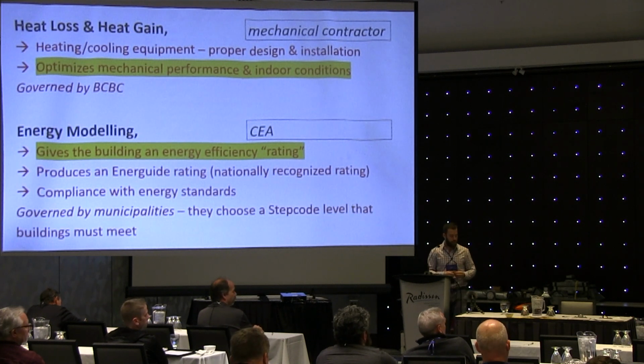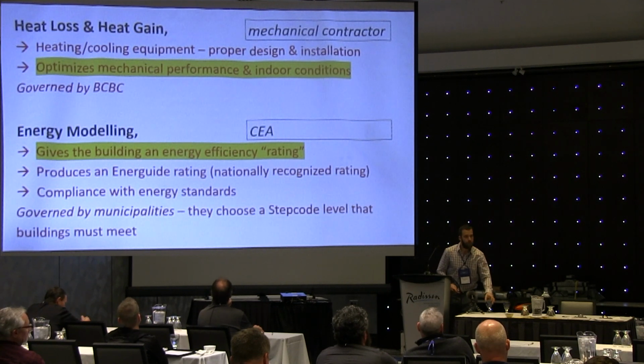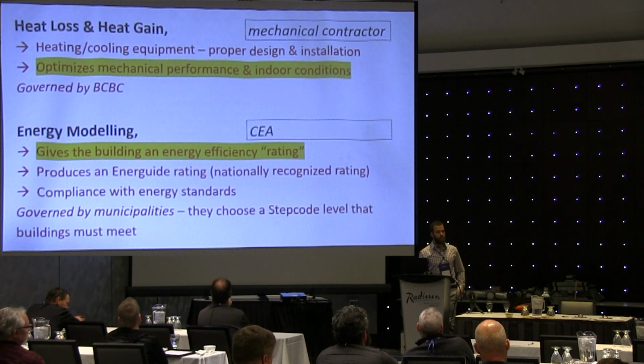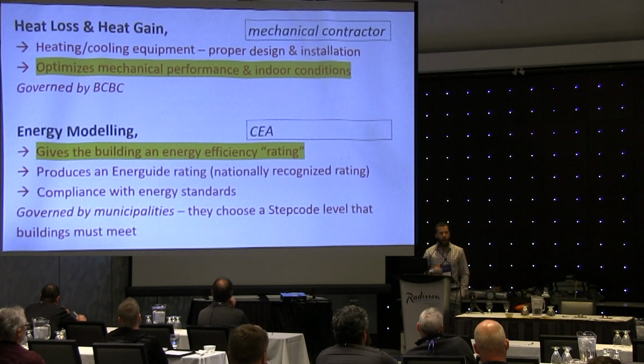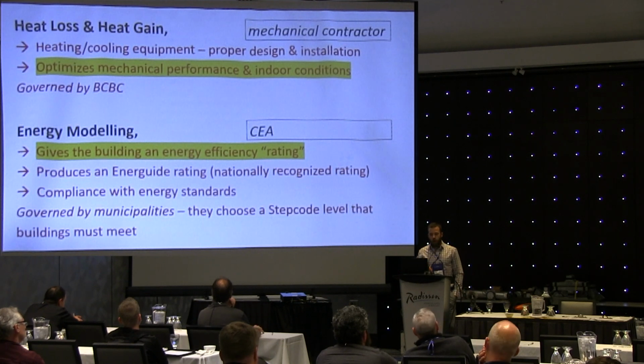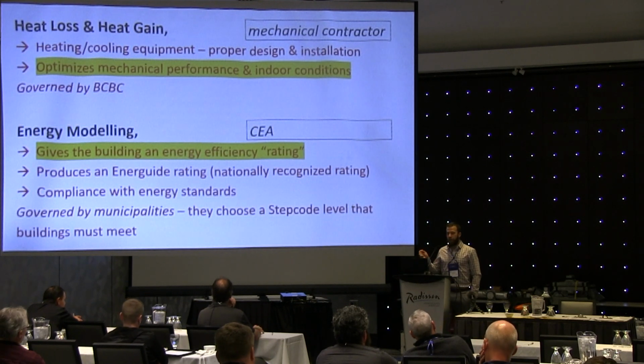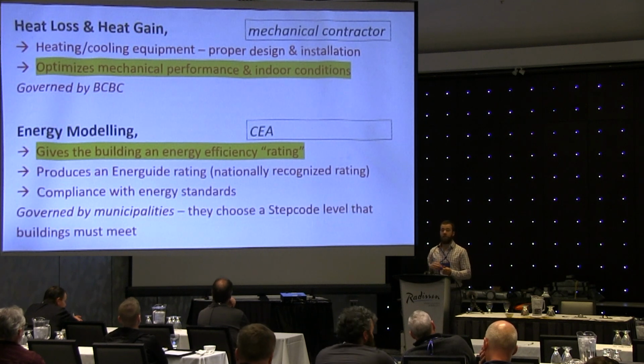Yeah? I use 2 words to help me understand this. The top is power. How much do I need for power in January to keep the house warm? The second one is how much energy am I going to gobble up over the 12 months? Mm-hmm. Power and energy. Yeah. So, like the heat loss and heat gain is worst case scenario, and you just get a value.